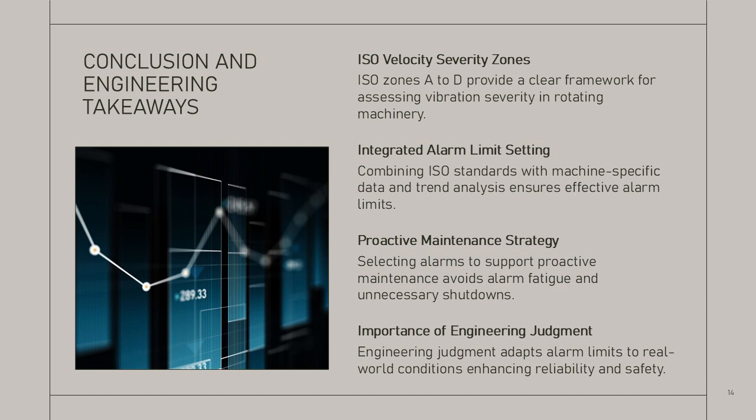Alert and danger alarms should be selected to support proactive maintenance without causing alarm fatigue or unnecessary shutdowns. Engineering judgment remains essential in adapting standard limits to real-world conditions. When applied thoughtfully, vibration alarm limits become powerful tools that enhance reliability, safety, and asset performance across industrial operations.